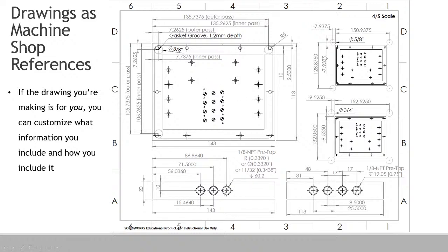And if you'd like to, there is a sketch tab within the drawings where you can add extra geometry to tolerance off of. I drew in some extra circles, which basically represented the diameter of the tool I was going to use, and dimensioned to the center of that to tell me the center of the tool in order to achieve this geometry. When it's just a reference for yourself, you can also do things that would definitely not be allowable on a proper manufacturing drawing, like if you're not exactly sure what drills the shop has available, you can add in the ideal size and the closest sizes that would still suit your purposes. Those sorts of things.